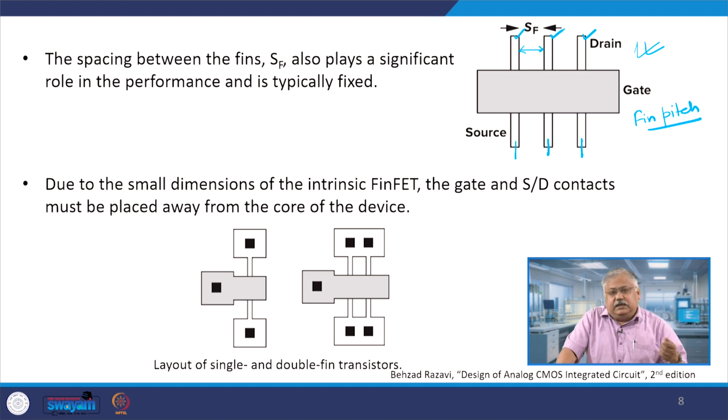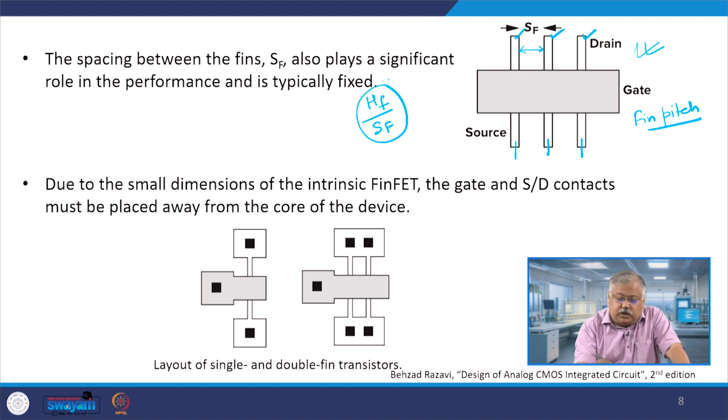But fin pitch is a designer-dependent quantity which depends upon how much area you want to choose and how many fins you want to generate within the same gate area, and so on and so forth. There is a critical ratio of the height of the fin to the fin pitch, and this ratio has to be maintained across all the FinFET devices. So, how much height you keep and how much they are separated is quite critical in understanding.